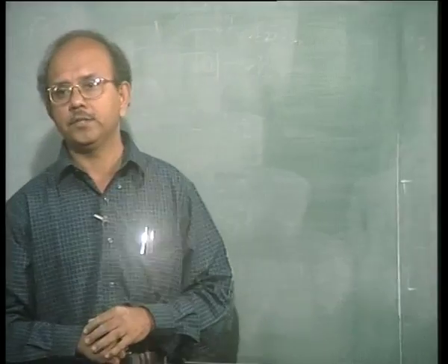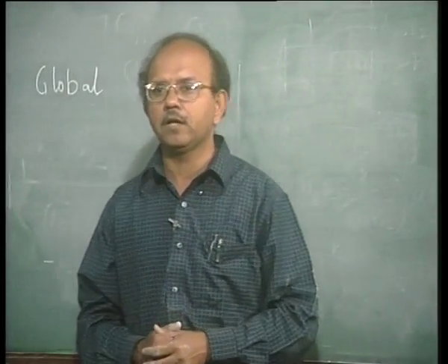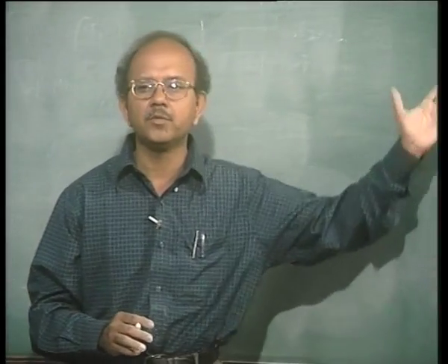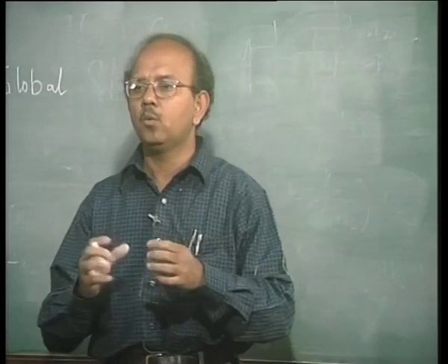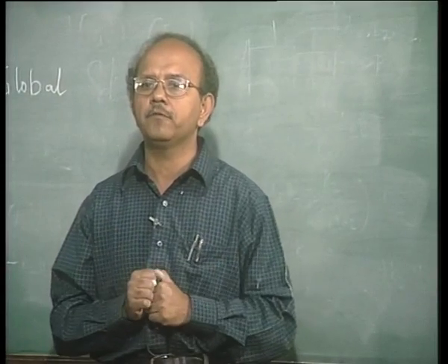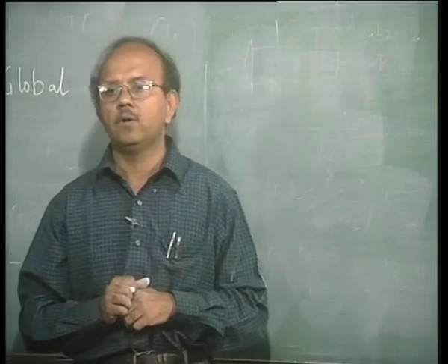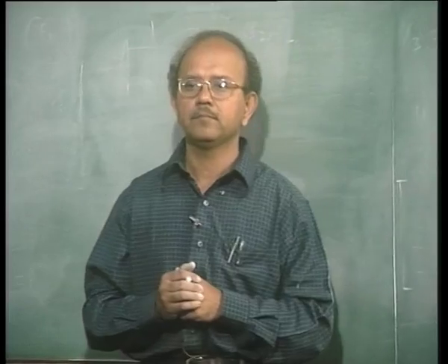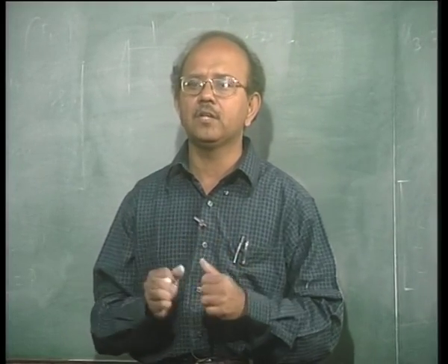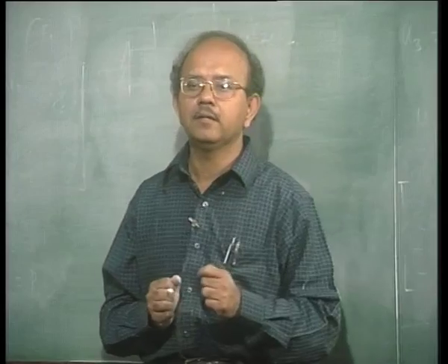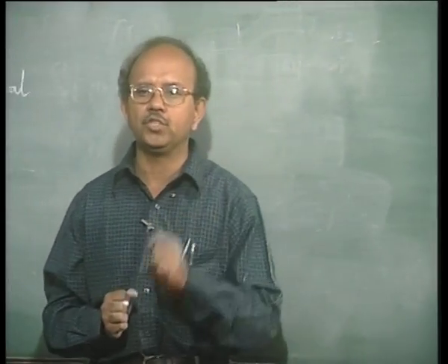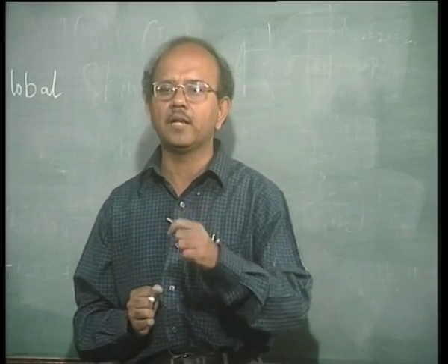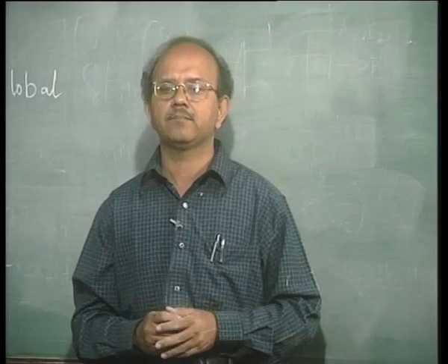What happens to the complex situation? Many of the examples which we saw the other day are definitely not in the class of example which we have seen. Or in other words, none of them are one-dimensional bar type of elements. All of them were 3D. Remember the railway wheel which we saw? It was a 3D problem. Now, in a 3-dimensional case, where the deformation is not also homogeneous, in the sense that the stress, as you had seen, varies from one point to another point, how do you define stress?